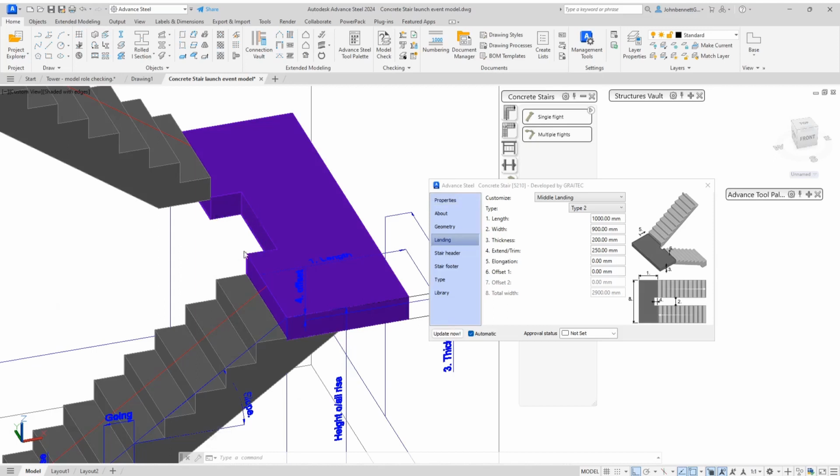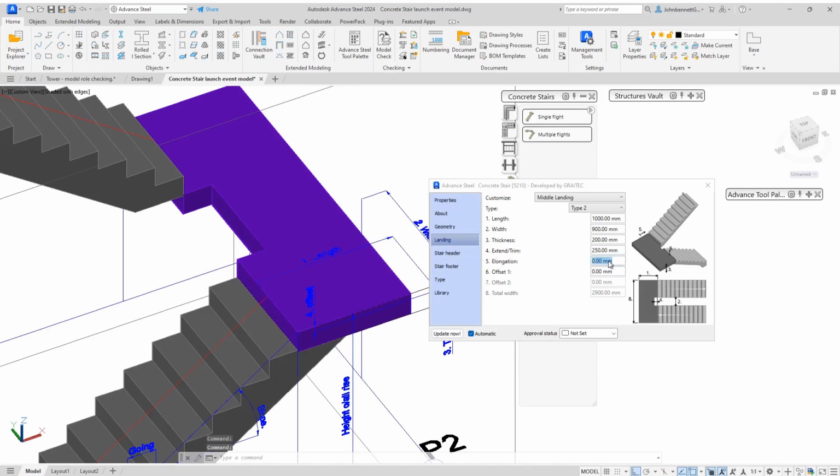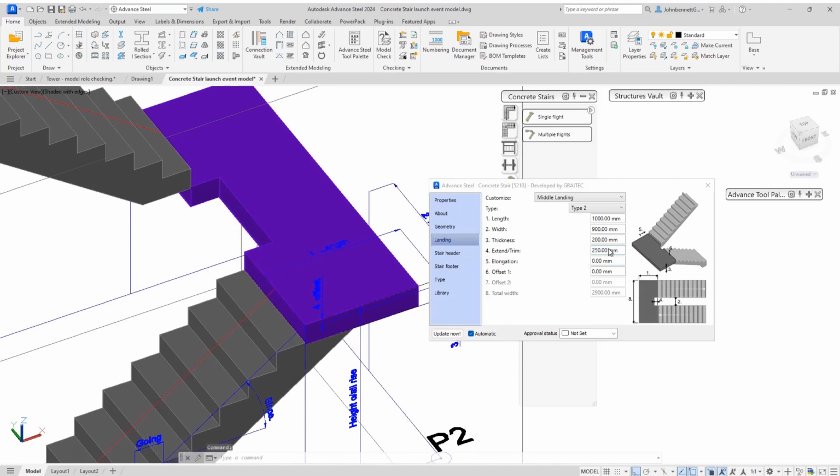So here you can put a further cutout in the center of the stair. I would call that the well of the stair, the internal part of the staircase. And again, that activates certain fields in there. You can control these in here. So if you so wish, these fields can become active. So we can alter these. So let's just change one of these. Let's just change this in here. And we can see there that obviously the inside edge here moved across. I'll just move it back again so everyone can see that. So if I just press enter on it, you see it drops back in there.